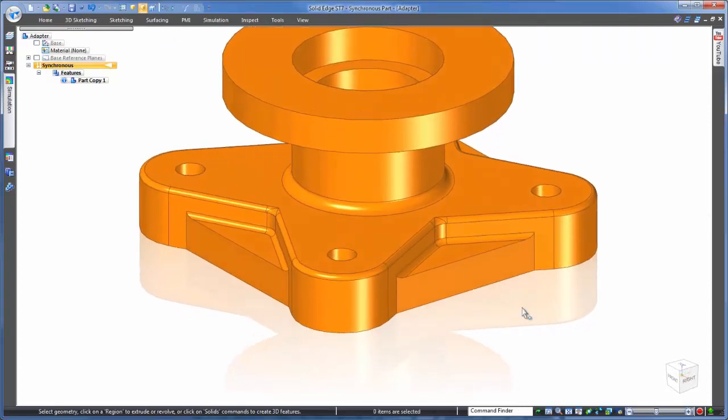Most other CAD systems rely on a history to be able to edit a model. But obviously, as this wasn't created in Solid Edge, we don't have that history, as you can see in the tree, or lack of it, on the left. Not a problem, and no need to do any convoluted feature recognition. Synchronous technology in Solid Edge allows us to make edits with a simple push and pull. This couldn't be any easier or intuitive.